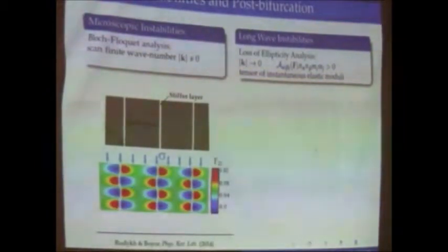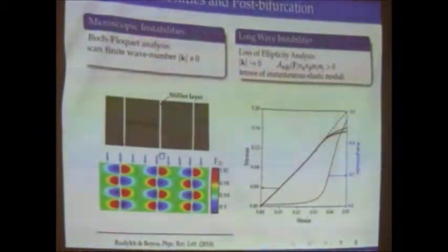With that you obtain all this information, then you can give it to the finite elements to find the right mode of buckling, and then you can carry out what is called post-buckling analysis, again with stress-strain. You can also measure the amplitude here. So you continue along this line, and then you have this buckling where you have the softening of the material, and that is where the amplitude of this wavy pattern starts growing.